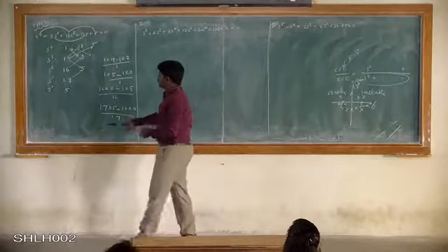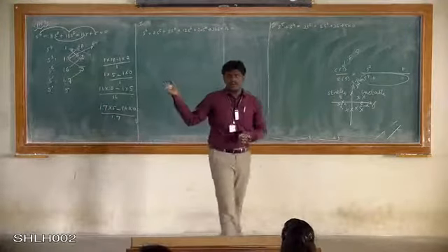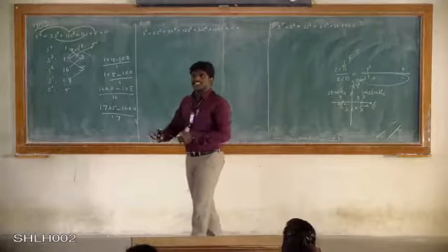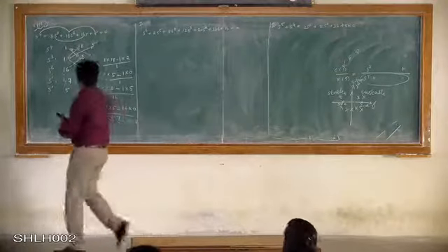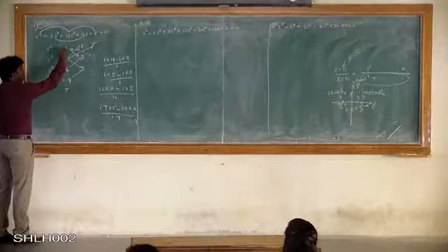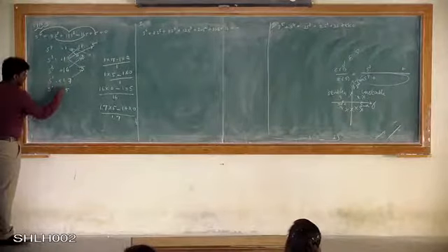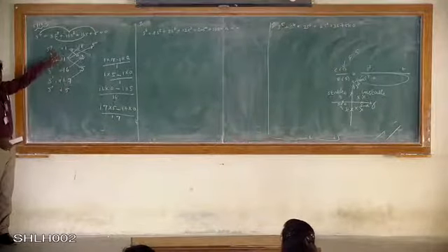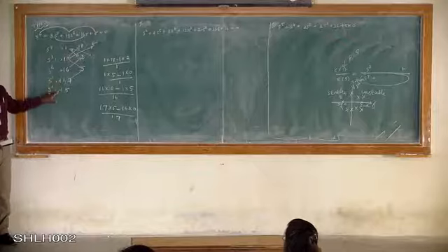Got it? So this is a Routh table we have made. Just by analyzing this Routh table, we will have to say whether the system is stable or not. Here, all these are positive values: plus 1, plus 16, plus 1.7 as well as plus 5. So there is no sign change. Plus, plus, plus, plus, as well as this also is plus.